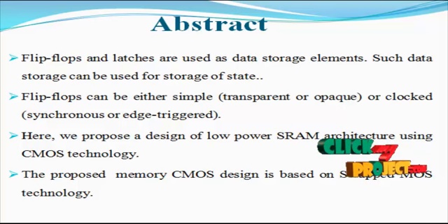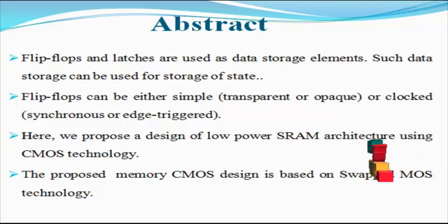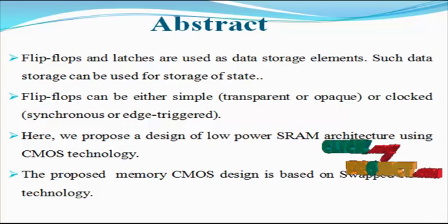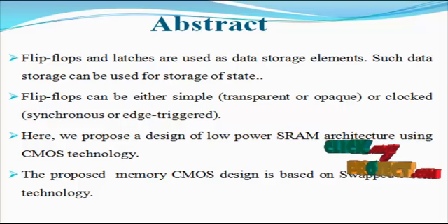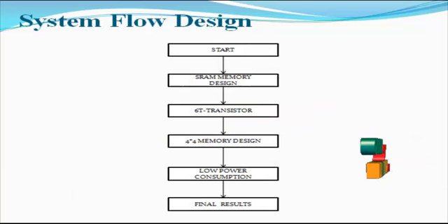The predicted area of these cells is significantly less, and the average read-write operation power is less than 25 times that of the conventional 6T SRAM based designs. The non-volatile characteristics of the cell make it attractive for non-volatile random access memory architecture designs.